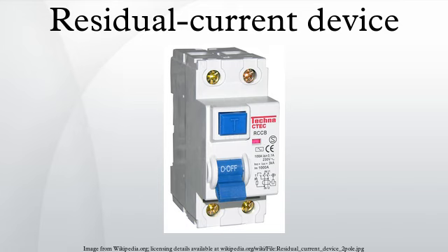North America. In North America, RCD receptacles invariably have rectangular faces and accept so-called decorator faceplates. GFCI outlets can be mixed with regular outlets or with switches in a multi-gang box with a standard cover plate. Arc fault circuit interrupters are required by current NEC code in locations such as sleeping rooms and incorporate GF protection. As a result, the slightly more expensive GFCI circuit breakers for load centers are less commonly used in residential applications.